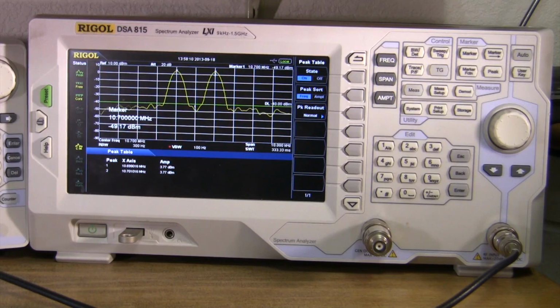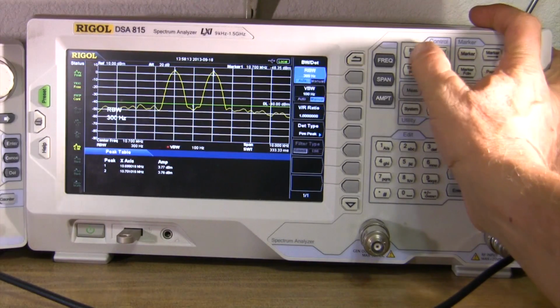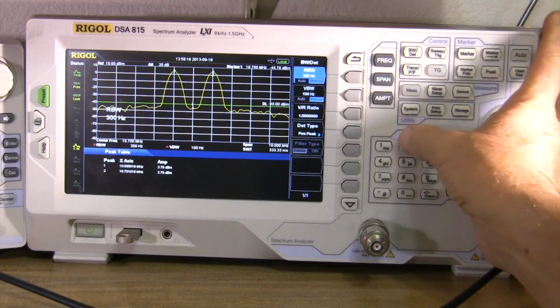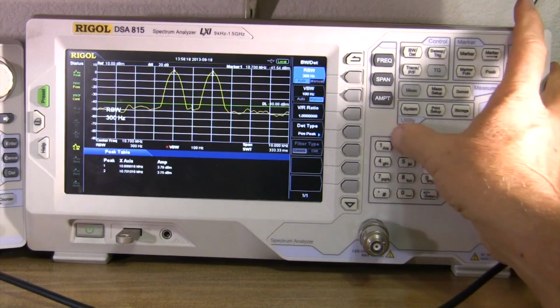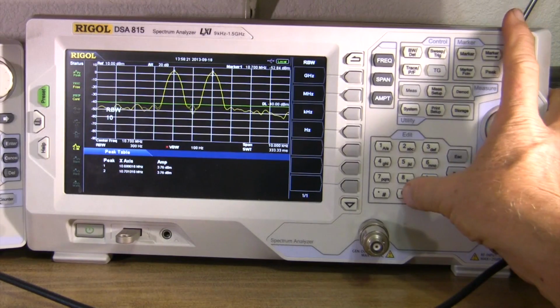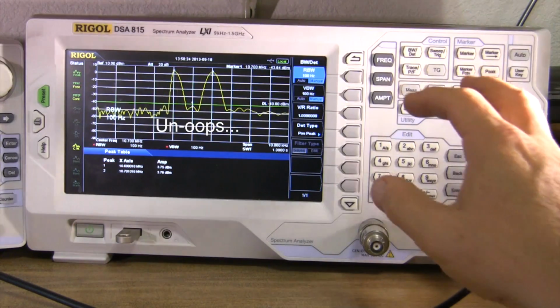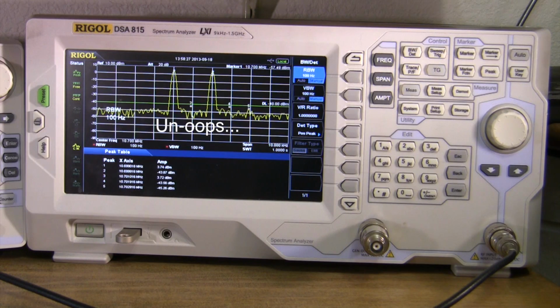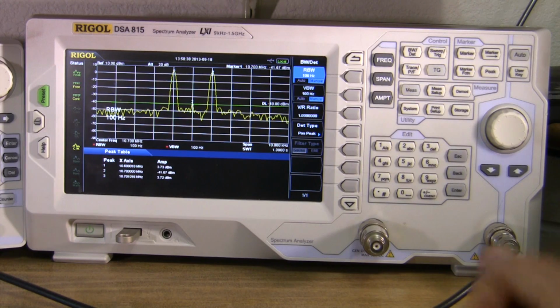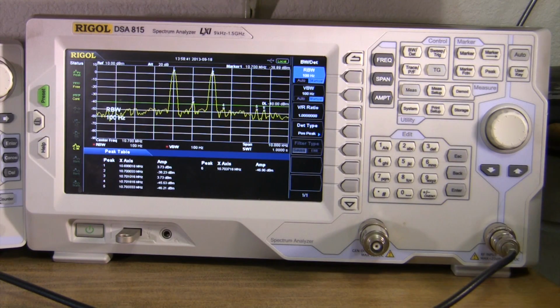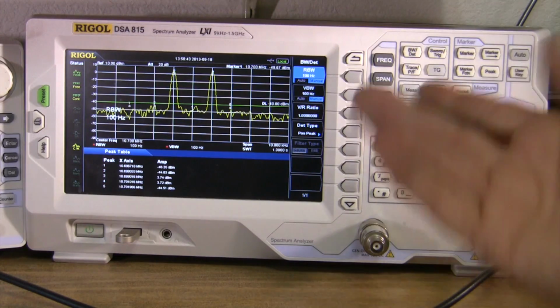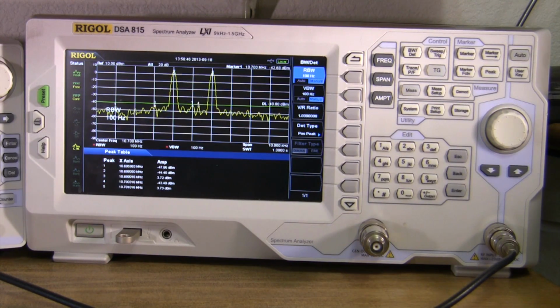So that's the way that works. Our resolution bandwidth actually did not change the last time. It should be 100 hertz. All right, much better. Sometimes I have to pay attention to what I'm doing here, because these cheaper instruments have buttons that don't necessarily punch when you think you've punched them. That's what apparently happened, or else I might have just stuck it over on auto and it would have gone back to 300 hertz. So at 100 hertz, we quite easily see the 2 peaks here.